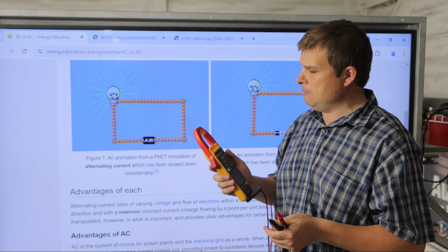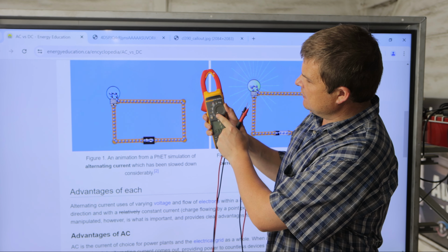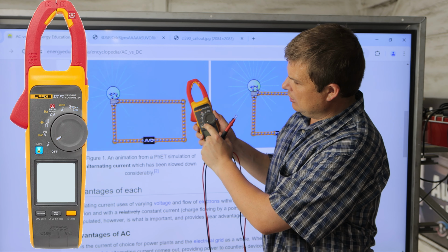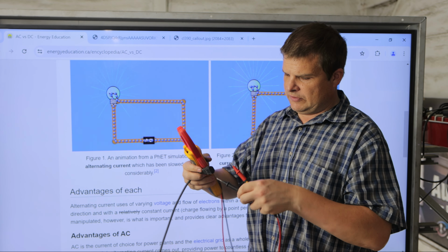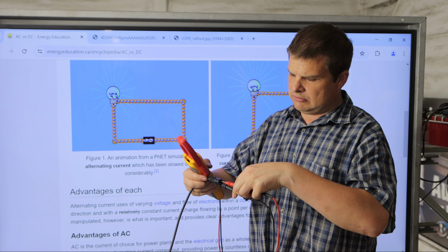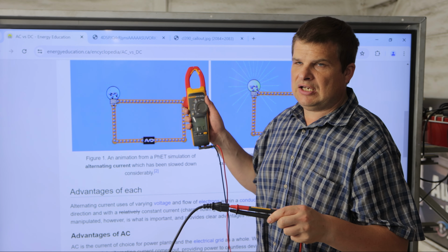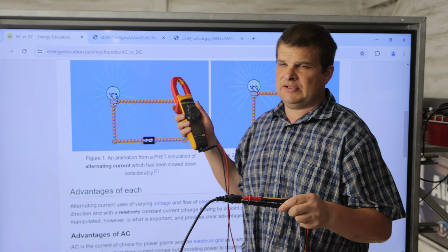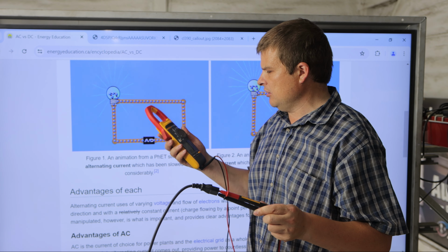And now we'll take some measurements. So the first step is turn your voltmeter knob. Let's do an AC measurement. So we want volts and alternating current. Here we've got a computer electrical cord. So we're going to start out by just plugging it straight in. Now it shows 105 volts AC. So right now, this should be closer to 120. It's hot today, and this is at the end of a long extension cord. So we're down to 105 volts.